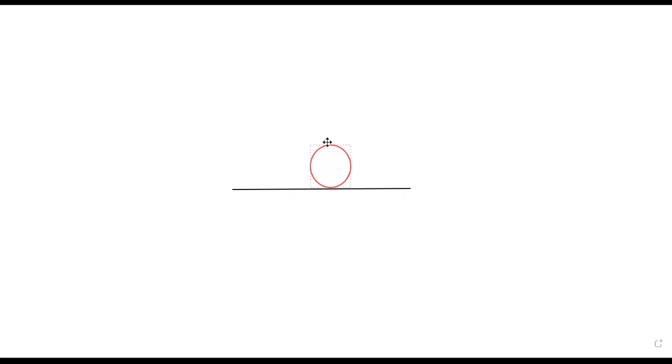So if this is the roller here in the original position, and now we displace it towards the right or left, the new position will also be an equilibrium position, and in each position the potential energy of this roller will be constant. So this third equilibrium, known as the neutral equilibrium, corresponds to the constant potential energy of the system. Okay, so coming back to our PDF,